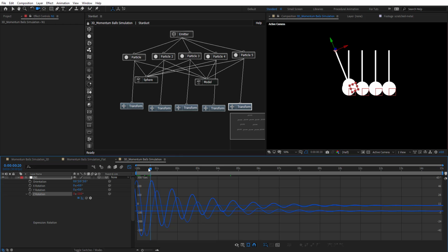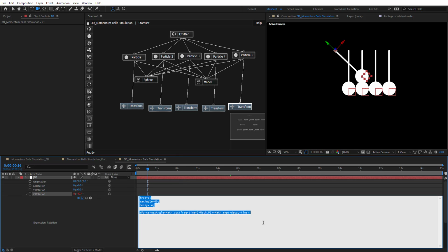So we're going to use the expression called clamp, and I explained it in the previous tutorial, so make sure to check it out. And so type here clamp, open parentheses, mForce, comma 0 comma maxAngle. And what's this clamp doing? Here we have the variable that we want to limit between 0 and maxAngle.